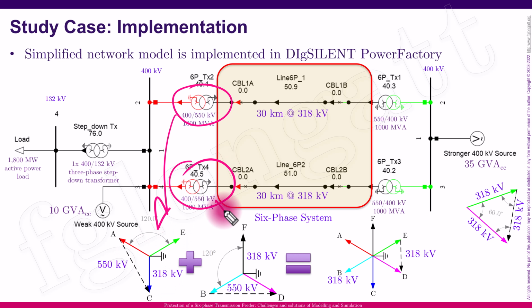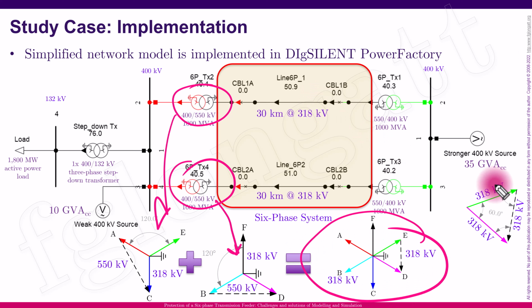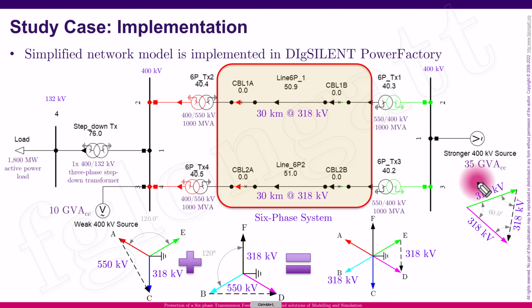The other one is creating the second three-phase system, and the phase angle between the two three-phase systems is 60 degrees. As a consequence, we have the magic of the six-phase system. And what is interesting is that line to neutral and line to line voltages for this six-phase system are equal, and that was a geometrical property that we already defined.